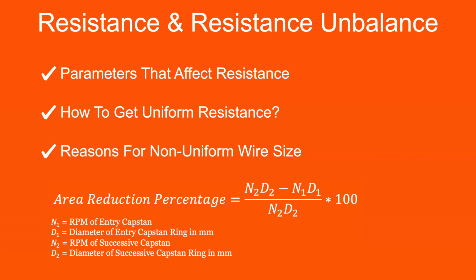The suggested steps will eliminate the excessive slippage and will improve the wire quality up to required level. The wire drawing lubricant should also be clean and should have continuous filter system to filter metal particles up to 5 microns. This will not only help in getting clean surface but will enhance the life of dies as well as drawing rings.